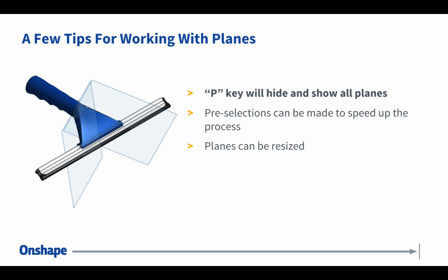Although the graphic of the plane may be a certain size, the plane itself is infinite length, and the graphic size doesn't have an impact. A lot of users will see a plane and say, oh, I can't construct outside of that box because that's the plane. That's not true at all. Planes are infinite length, and you can change the size of the plane, but it's more of a graphic representation. It doesn't really have an impact on the design itself.